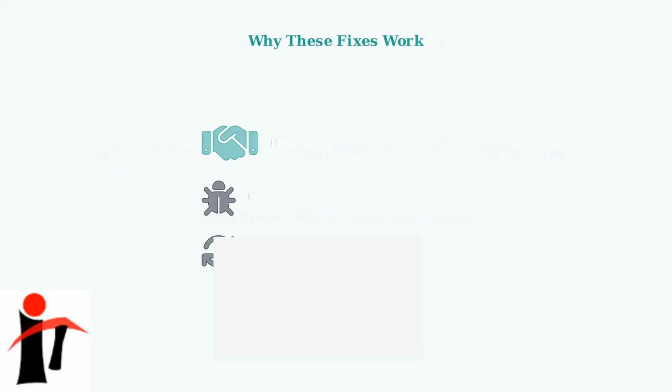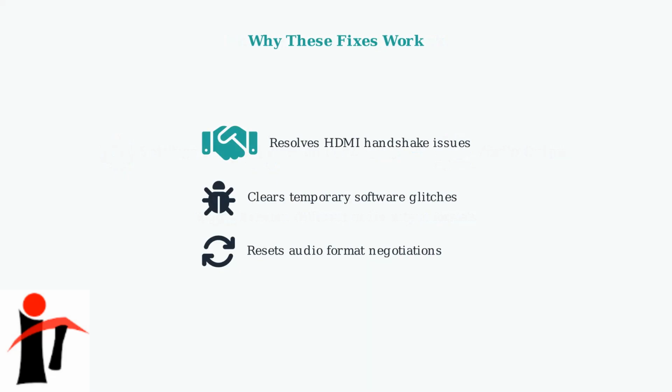These quick fixes work because they address the most common causes of YouView sound problems: HDMI handshake issues between devices, temporary software glitches, and audio format negotiation problems. Most users find their sound restored after trying these simple steps.